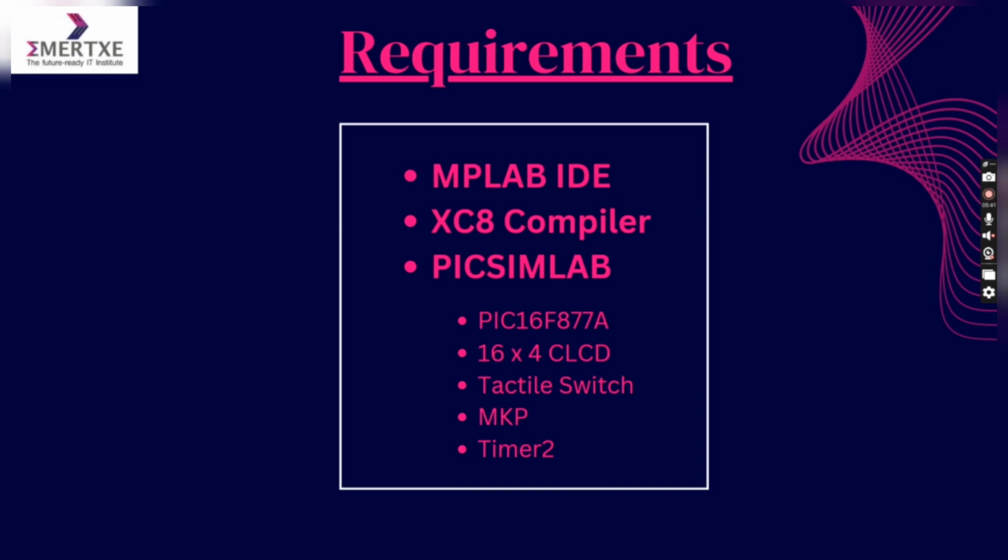16x4 CLCD display. This character liquid crystal display will serve as the user interface for our microwave oven. Matrix keypad, MKP. This will be used for user input, allowing the user to select different modes and enter cooking times. Tactile switches.